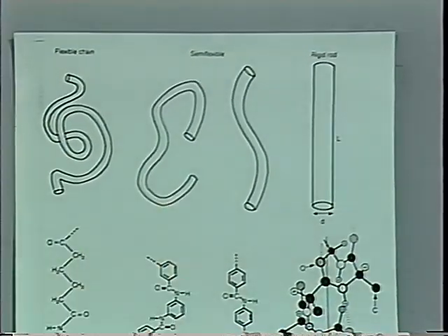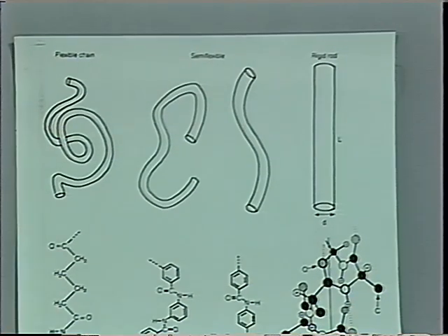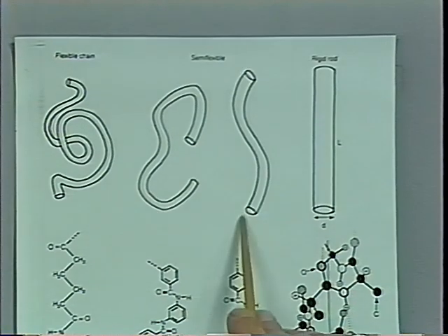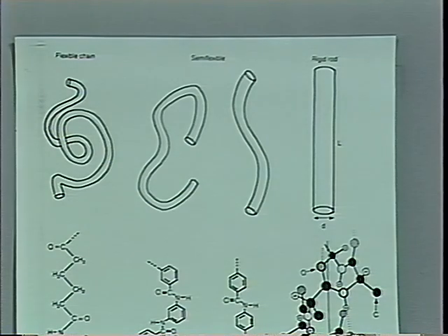The stiffness of the molecules hinders the rotational diffusion, so those molecules cannot rotate as freely, but they can translate very freely, at least in most cases. So that's where the lack of positional order comes from. They're translating pretty fast, but they cannot rotate. They are easy to orient in flow, and they already have the extended chain conformation, which is advantageous for achieving extreme mechanical properties. And in fiber spinning, that's used for instance.